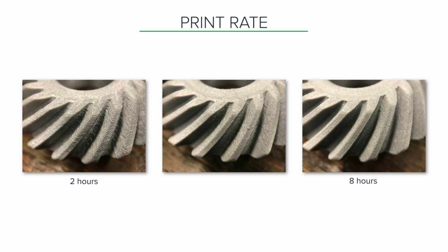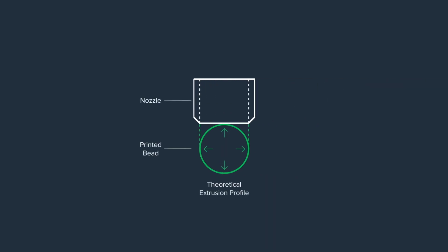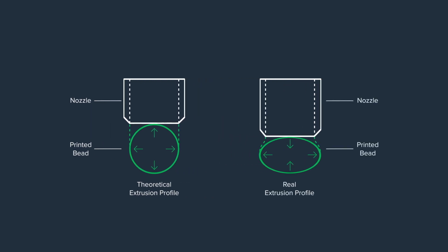It's also important to recognize the connection between the process physics, the deformation and flow of the material in this case, and the part properties. In extrusion printing, you might think that the cross-section of each bead in each layer is circular because the plastic comes out of a circular nozzle. That's not true because the nozzle actually applies a force to the molten plastic as it traces through each layer, meaning that each road, as we say, is actually deformed, more like an oval. And this deformation is critical to the microstructure of the part.